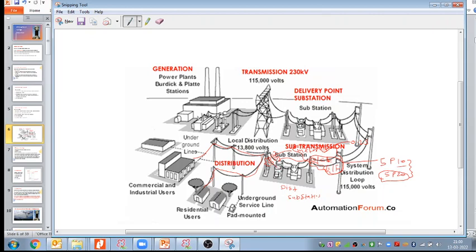Then if this is a transformer here, for the transformer protection, this incomer, this is outgoing from the transformer. So how many CT cores should be here, and what should be the protection class? Similarly, we need to specify for this, which is again one grid substation.